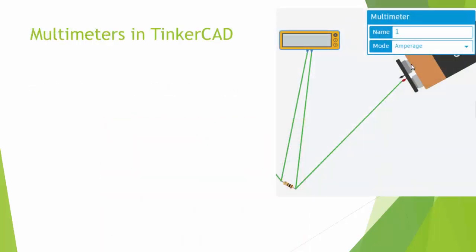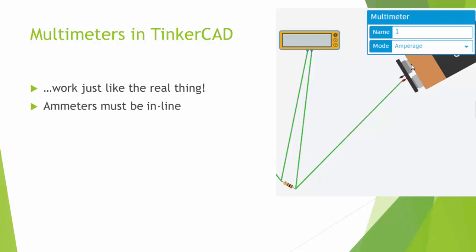Okay, we can also use multimeter functions inside Tinkercad. So it has its own multimeters, and these are useful for practicing. We lose a few tricks, like we don't know about pressing very hard onto the leads and things like this, but that's okay. It will still show interference if you try to measure resistance with power on it and stuff like this. So if you're using Tinkercad, it'll work very much like the real thing.